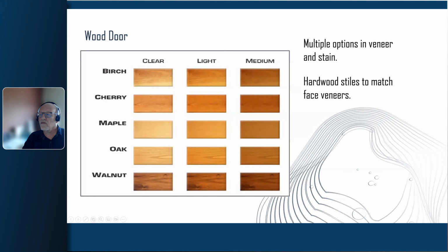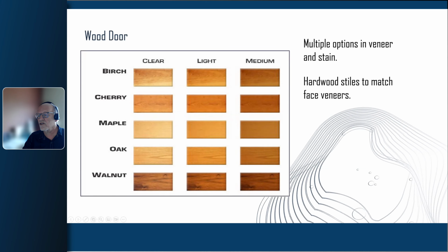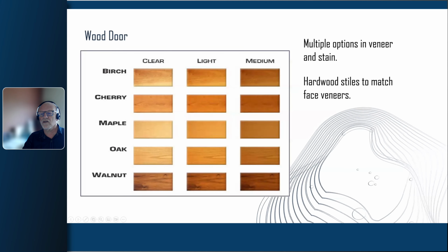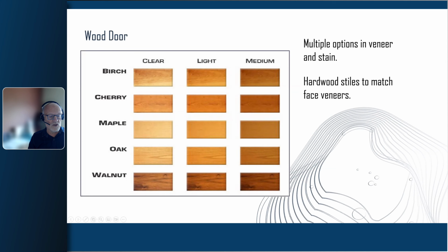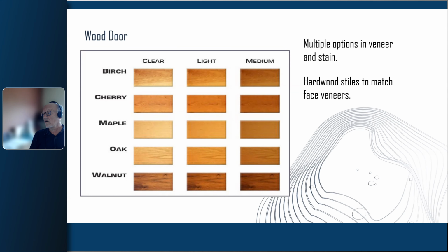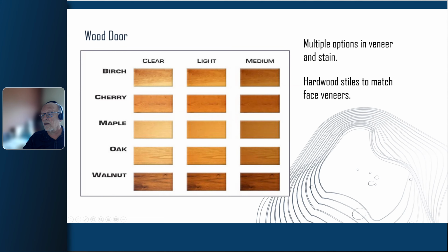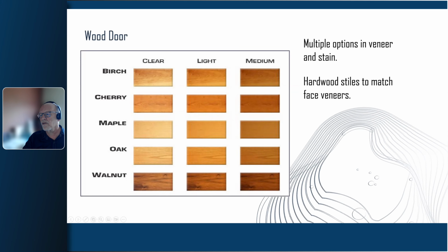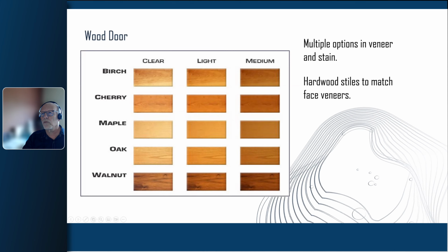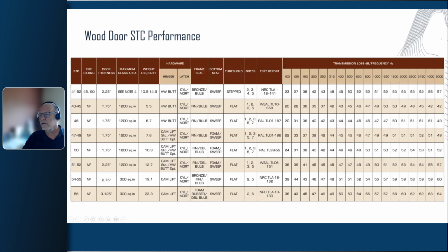This is something about veneer finishes, of course, we're going to be very interested. Basically, you can get any finish that you want that's in conformance with the rest of the project. So again, going back to my favorite example of K-12 area, you've got maybe 500 doors in the school, of which 30 are acoustic. You got to match the veneers, you've got to match the finishes, and that's what this is saying. You can do that using different manufacturers. Of course, you're used to that with different millwork suppliers as well.